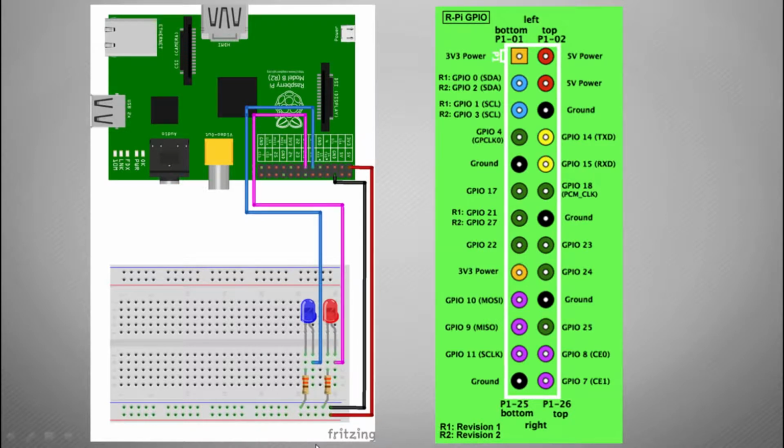What you can see here on the diagram is we have represented our breadboard. We have a power cable that plugs in from the Pi to the red line here. We have the black line, which is the negative line, or the ground. We have wires going from our pins to our LED, and then the LED links down to the ground, and in between there we have a resistor which restricts the flow of current.